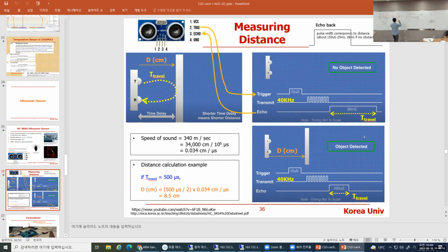So by default setting, the issue is that in the ISR you have to clear that bit. Then things will work fine, whether you set this interrupt to level or edge trigger.